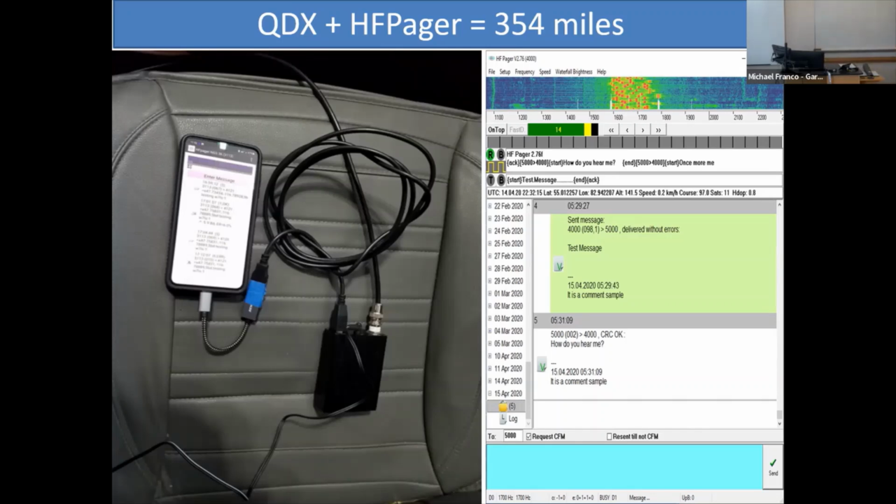Wow. So here's a smart amateur radio hobbyist. He says, wait a minute, I could get this distance with WSPR. I know how they're doing it. How are they doing it? Narrow bandwidth, 10 hertz or less. They're using a certain number of tone modulation, which he's doing, and it's very slow. He slows everything down. These are messages, right? They're not video, they're not audio, so he can go slow.